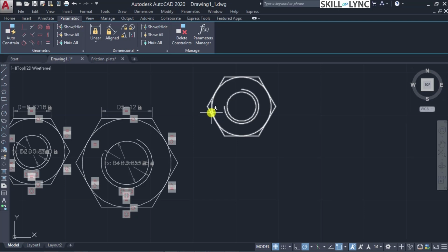Okay, so even though the reference of this object is the same as here, you can see that you don't have the flexibility to edit the dimension references that you had. And also, if you update the dimension references, what happens is all the block references, that is, all the blocks in this drawing that bear the same name, will get updated when you modify this drawing dimension. So in order to avoid that, we have one feature called dynamic block settings. Here we can modify the block dynamically using certain key parameters that we wish to look at. So we'll go ahead and do it.